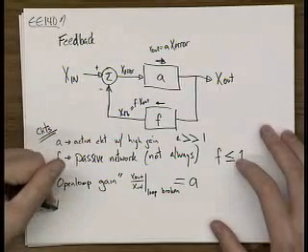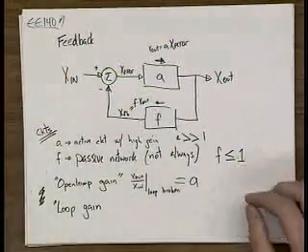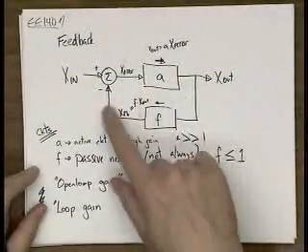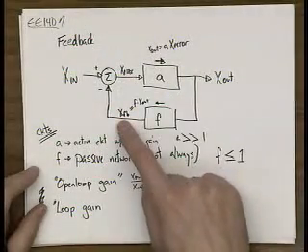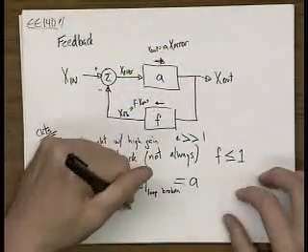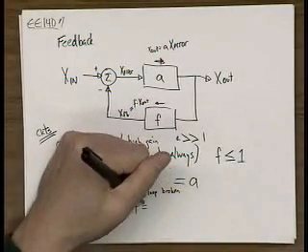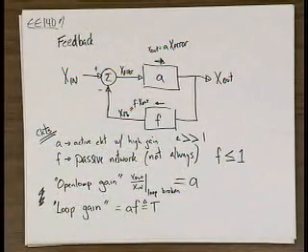There's also the loop gain. The loop gain is basically traverse the loop. You can see that there's a feedback loop here, and calculate what the gain is around the loop. So you start at X error and go to X feedback. That's basically the loop. So you can see that the loop gain is equal to AF, right? Sometimes, in Professor Broderson's notes and in a lot of books, the loop gain is called T. Okay? Yes? Does that, everything's instantaneous when you're talking about a loop like that, right?